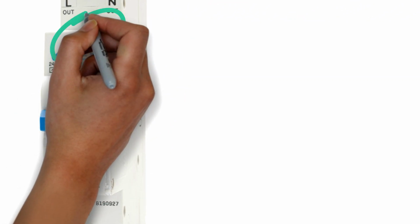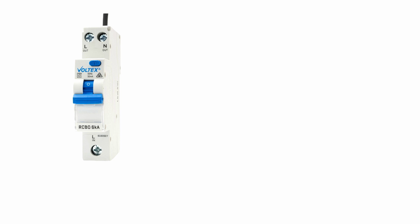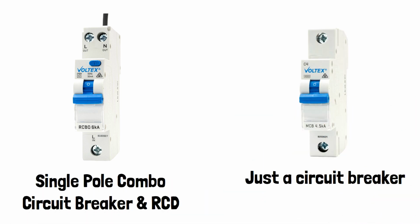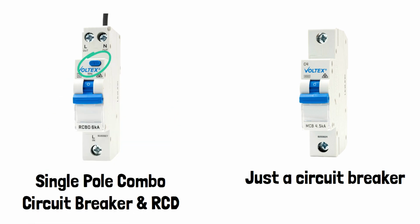That's what gives it away that it's an RCD, whereas a circuit breaker doesn't have these buttons. So that's a single pole combo RCD with a circuit breaker built into one. That is just a circuit breaker on its own. So always look for that test button. These are normally found in residential or smaller blocks of units, maybe inside the individual units. You'll find this style of RCD combos.